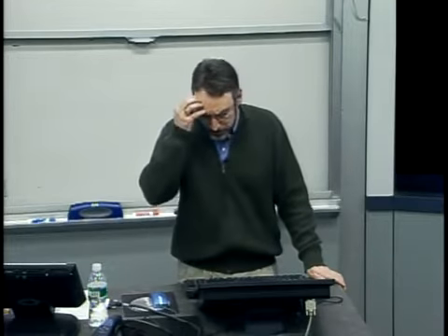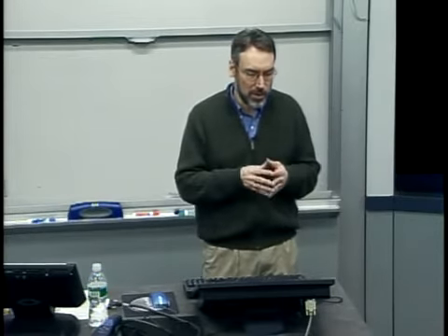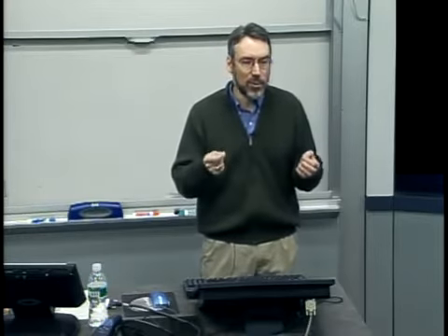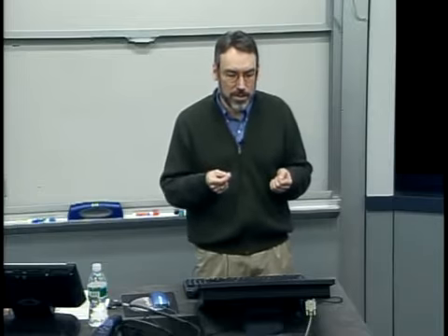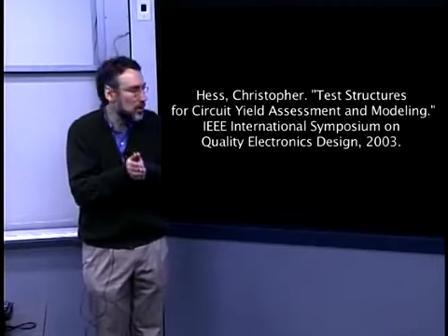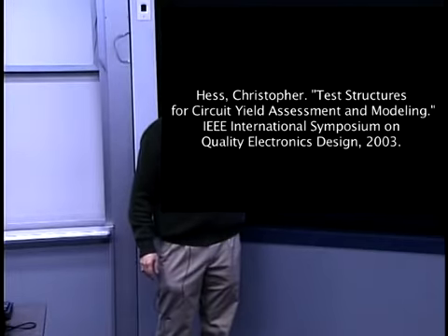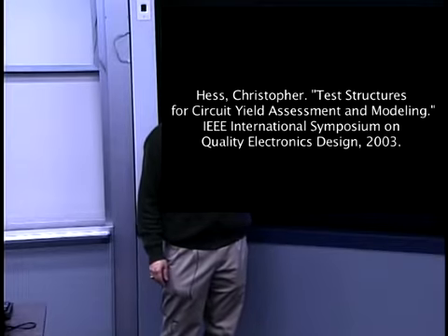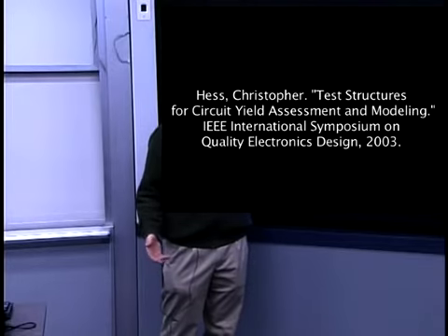Now, I mentioned this a little bit last time. It used to be 10 years ago, 15 years ago, if we talked about yield, the percentage of functioning devices that came out of a semiconductor fab, the main worry limiting yield was particle defects. And you can imagine we're talking about very, very small features here. And if pieces of extraneous matter were to fall between, say, two metal lines, that would cause an electrical short, or could cause an electrical short, and now the device does not function correctly.